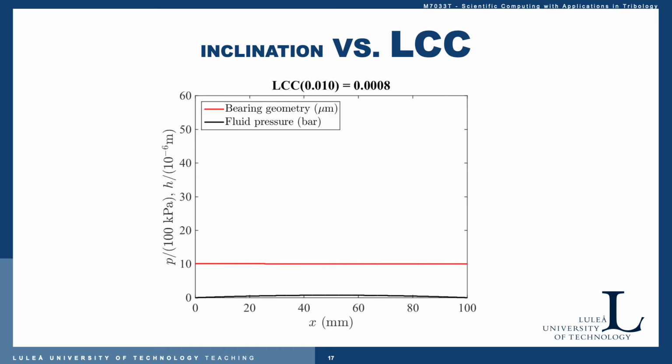So it's very small, okay, dimensionless number, but the dimensional version is huge due to that it is scaled with 1 over the exit clearance squared. And the exit clearance is of the order of micrometers, very small. And therefore LCC in reality is large.